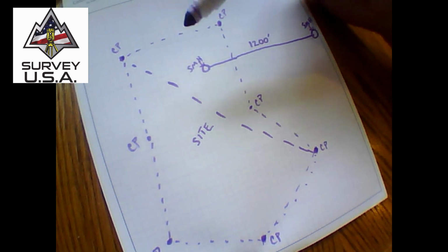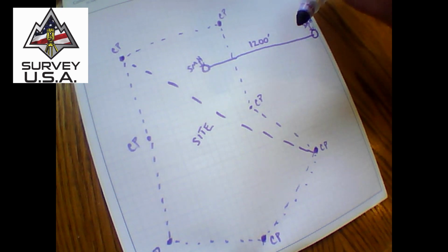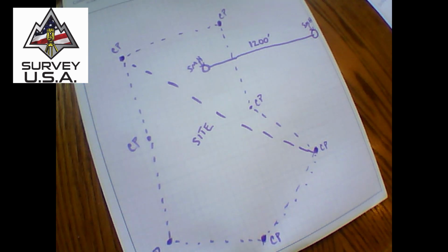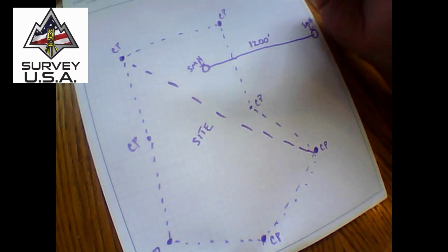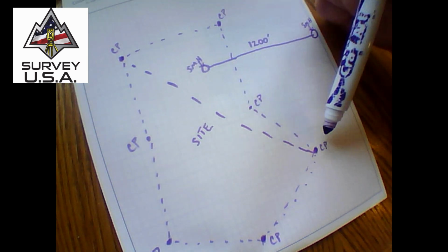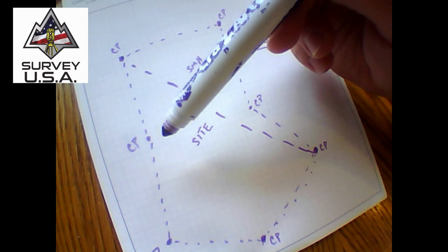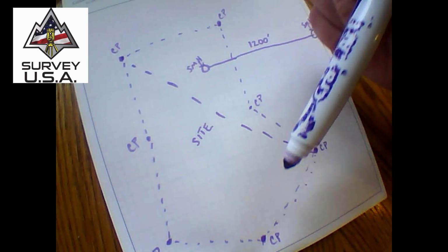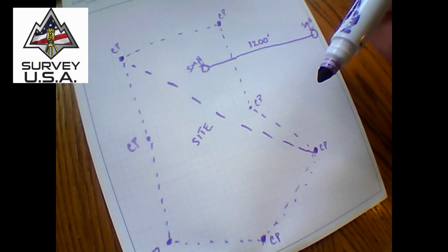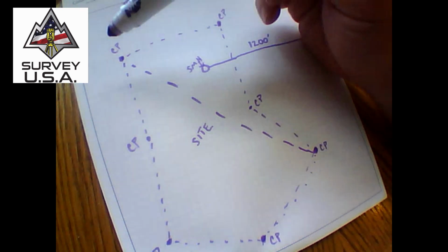So now that you've got your site calibrated, you're extremely worried about vertical, of course. It's a construction project. We need to have good vertical. Another situation: people calibrate to every exterior point vertically as well. I do not like to do that. If you are going to do that, use every single point. I've seen guys make a fatal mistake of calibrating vertically to 2 points.